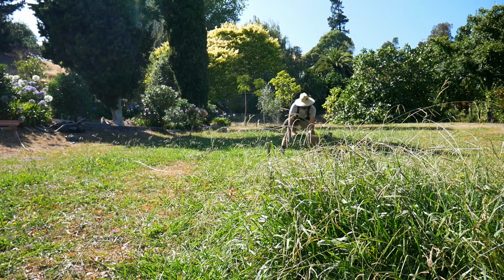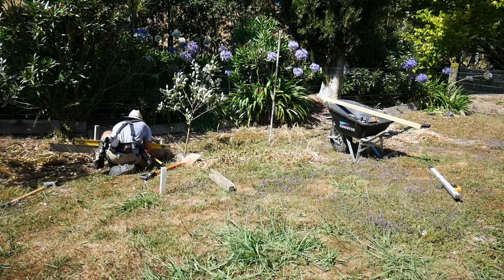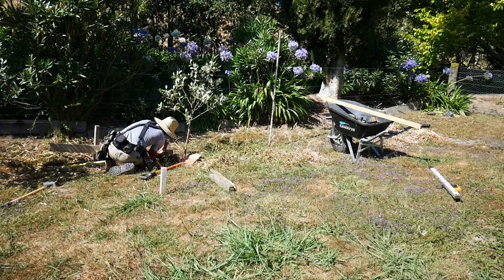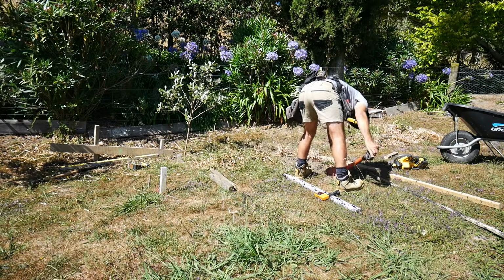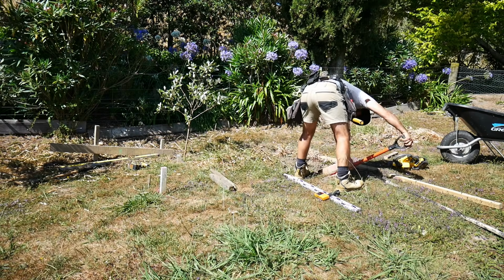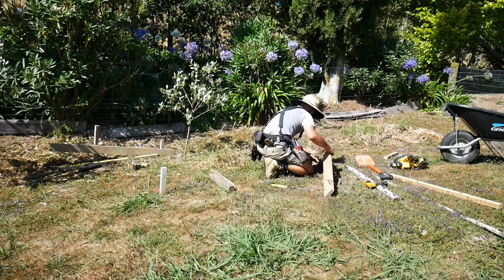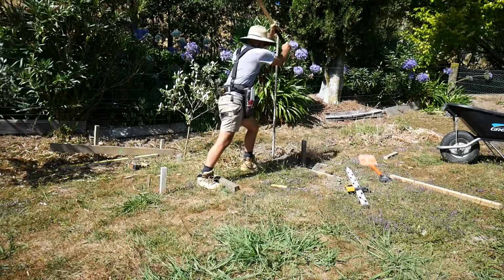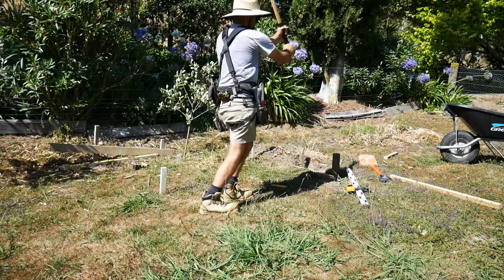Now that I've located where the house sits, I need to build profiles to carry my string lines. A basic profile is a temporary frame built with some stakes in the ground and a horizontal rail known as a batter board. They are built outside of the corners of a building, and the string lines that represent the building outline are tied to them. It also helps if they are built to floor level.